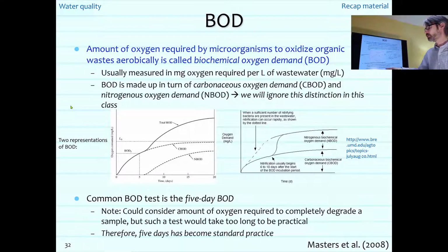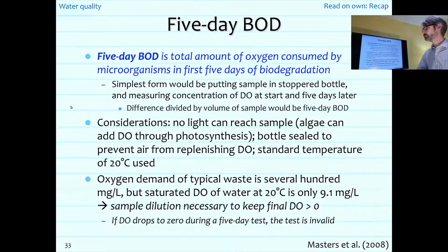Now, we could actually consider the amount of oxygen that's required to completely degrade a sample, but such a test would take quite a long time. It would be too long to be practical. And so 5 days has just become the standard practice. There's nothing magical about 5 days, it's just the standard practice. It does mean that the NBOD has not typically started yet, so it's just the CBOD component. The 5-day BOD is the total amount of oxygen that's consumed by microorganisms in the first 5 days of biodegradation.